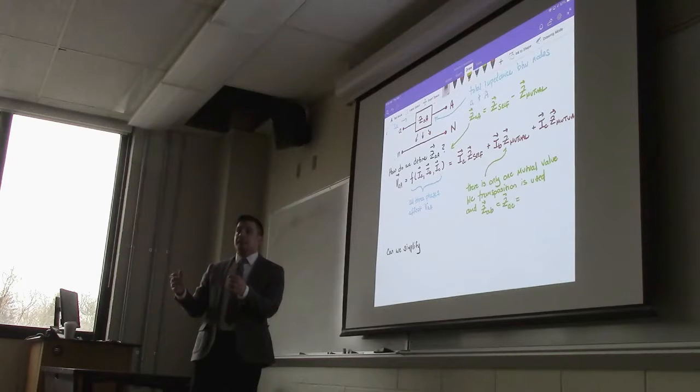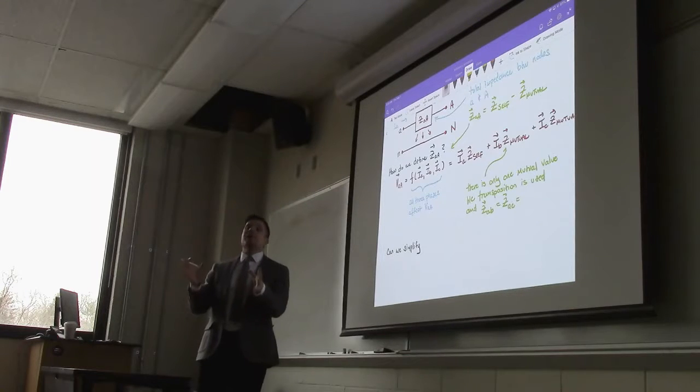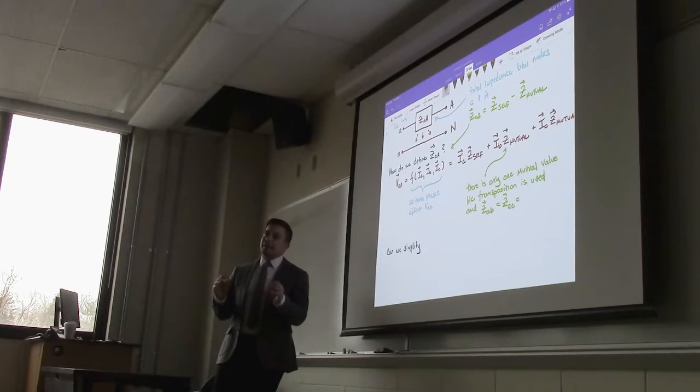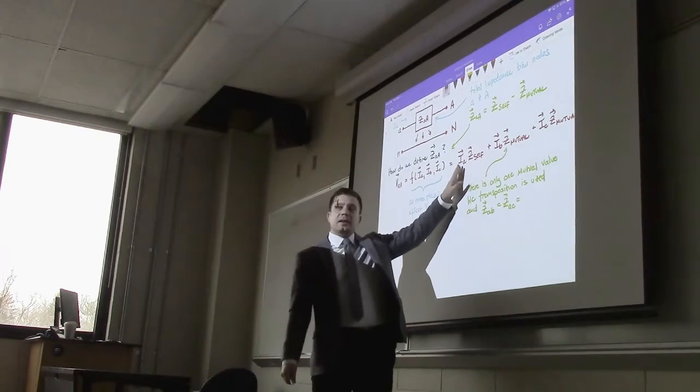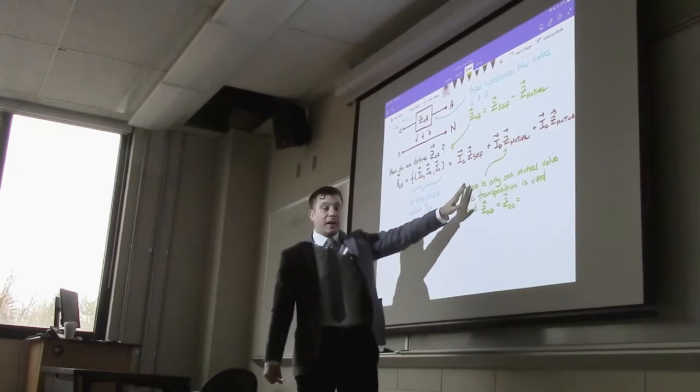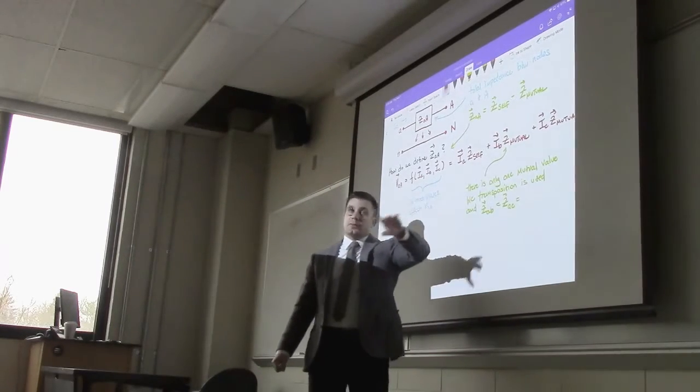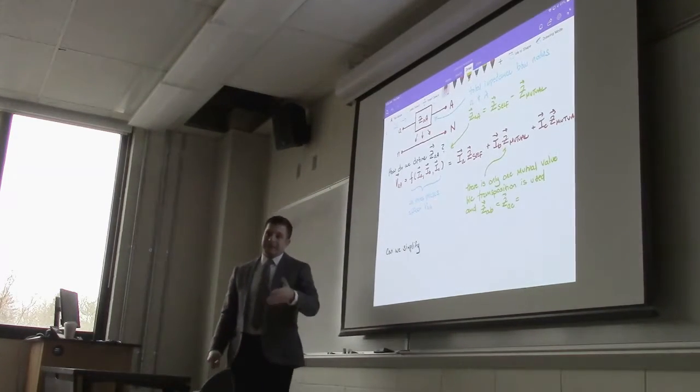So, if it's close enough. It's really hard, and I probably don't want to use the wrong language here, because this is not really part of the lecture, but that's the best way of looking at it. Think about this as the impedance that would be there even if it were by itself, and there were nothing else, and then these two are associated with the coupling between the phases. Okay, that kind of cleared up?